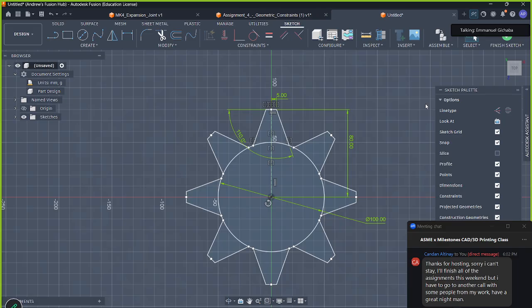I had a question about the angle. Sure. I already had my dimensions constrained, I think, so I made the angle driven. How do I change it so the angle is the driver instead, and that would change the length of the lines? That means there's some kind of over constraint somewhere. Either you might have to delete one of the other dimensional constraints that you've already created, or you're going to have to find some geometric constraint that might be preventing you from changing the angle.